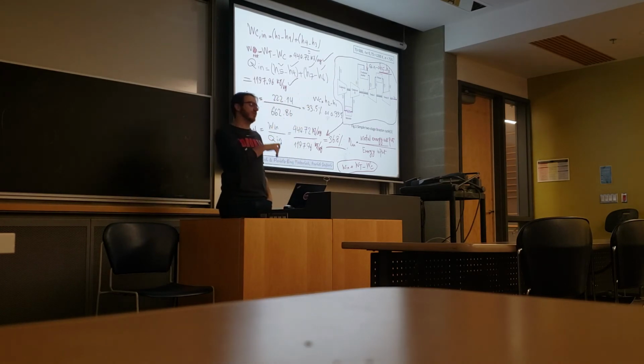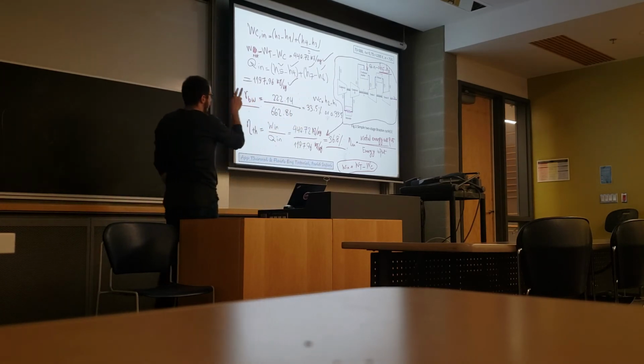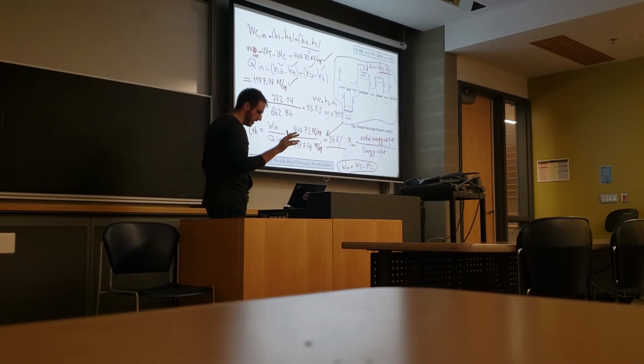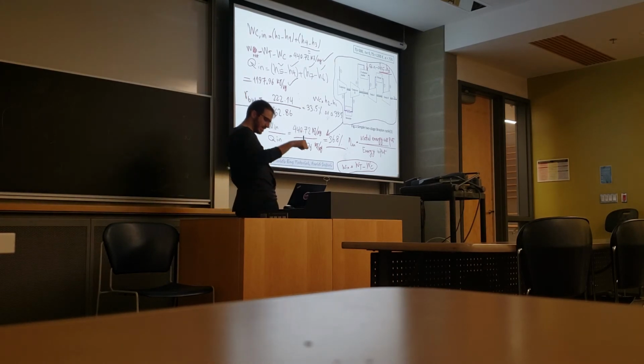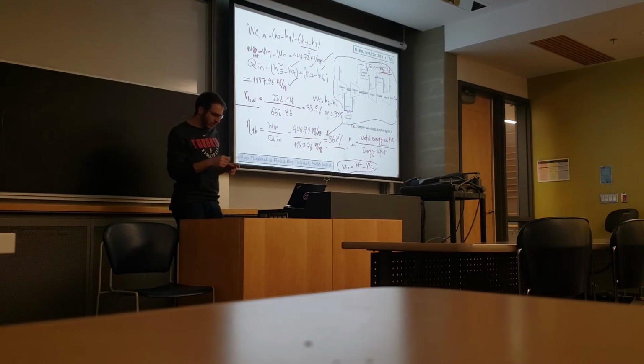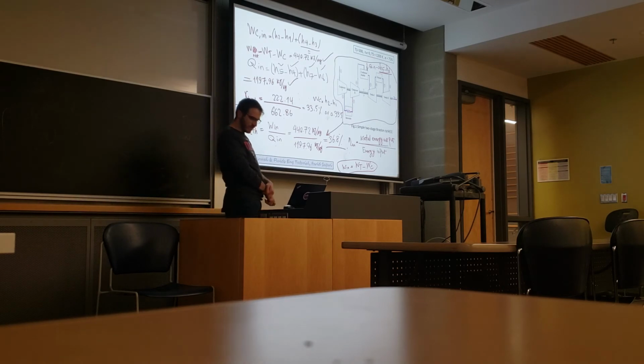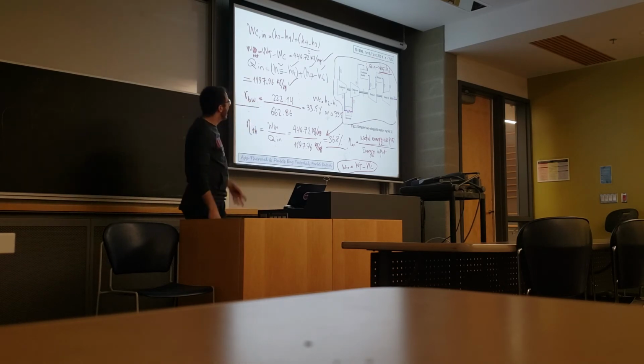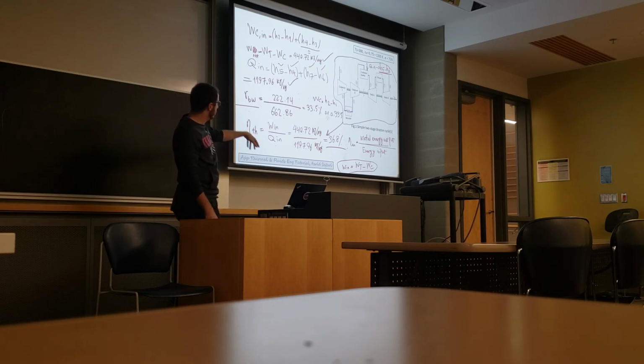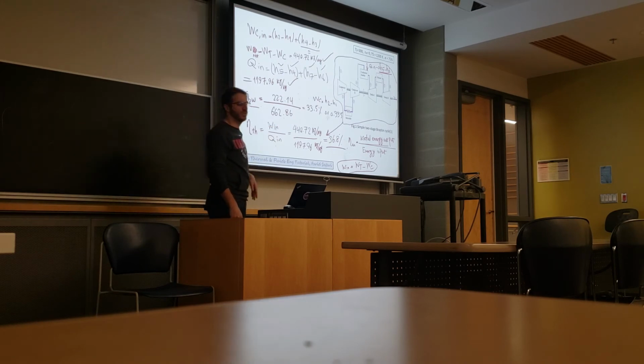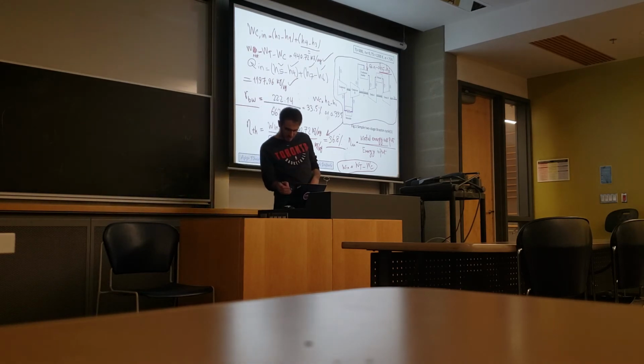So just keep that in your mind. So basically when you have it without regeneration, without heat recovery. So in the next case, we will go through a regenerative system. But in this case, we have usually the thermal efficiency of between 30 and 40%. So here, 36.8. Any question?